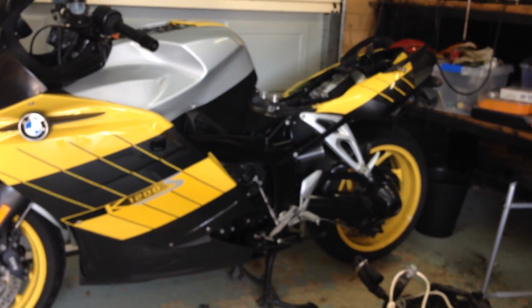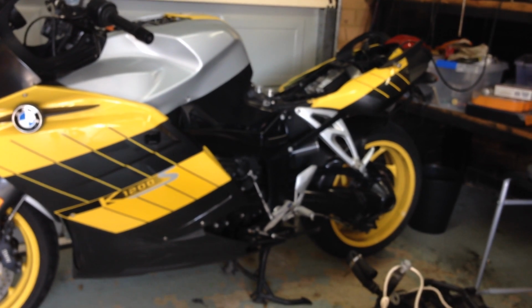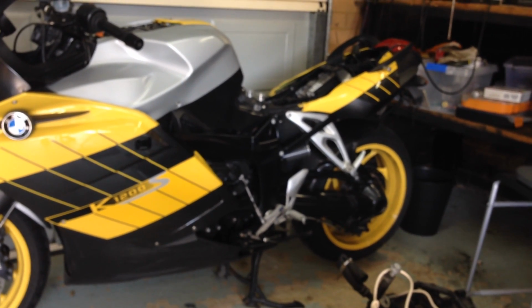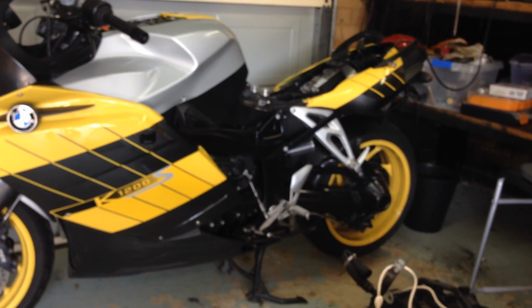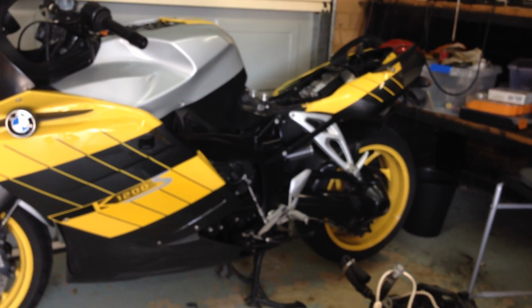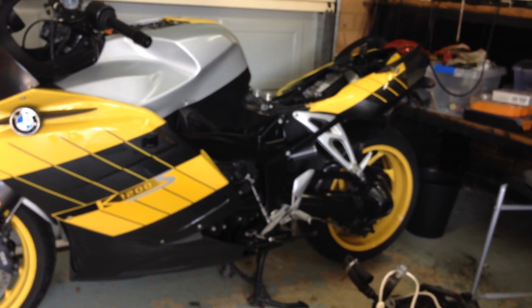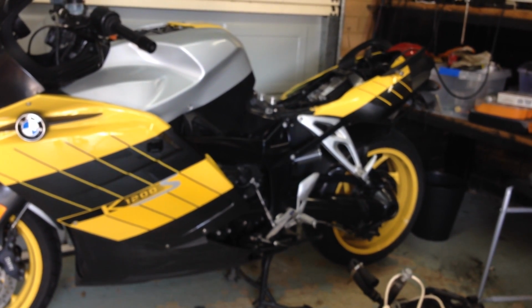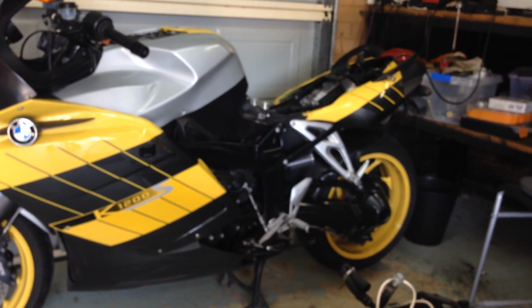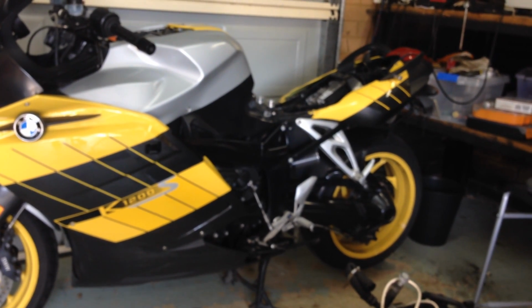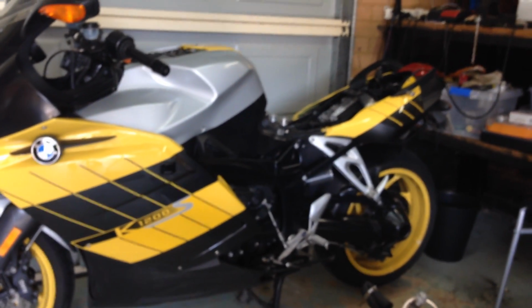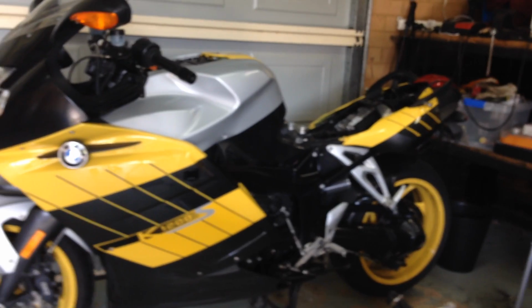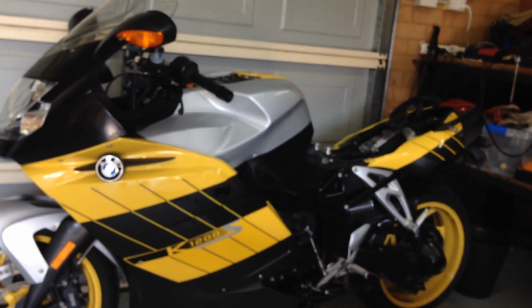So this is my personal opinion about the servo assisted ABS. It works. It works great. I flush my system once a year. BMW recommends to do this every 2 years, but winter time, it rains, I got nothing else to do, I might as well go in the garage and do the maintenance. In my last flush I used half a liter of brake fluid, so that's not really that expensive. It's just a bit time consuming. You have to take off all the fairings, tank, everything, and use the software that I'm going to show you later.